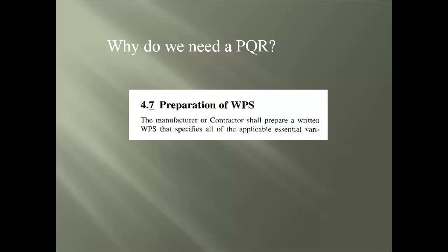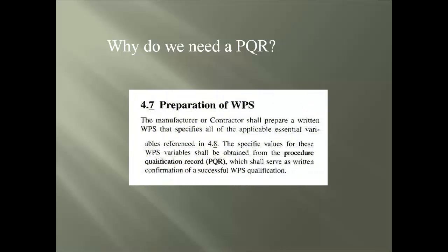Next question is, why do we need a PQR? Section 4.7 of the D1.1 states the WPS shall be obtained from the PQR, and the PQR shall serve as the written proof of a successful WPS qualification.